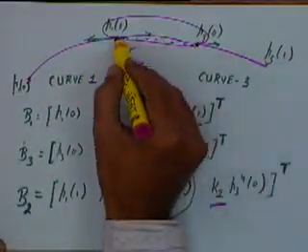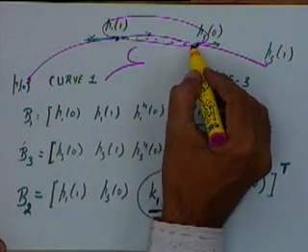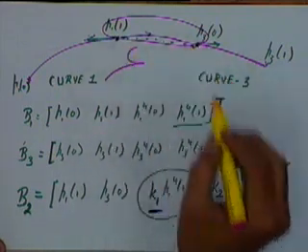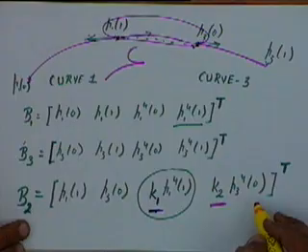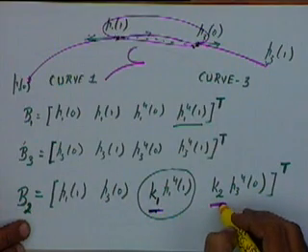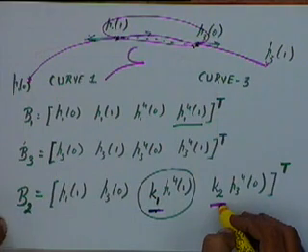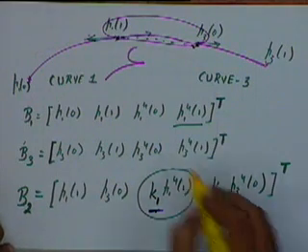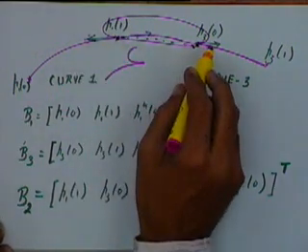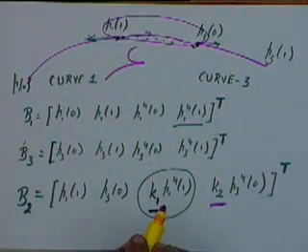Okay. So in this particular case, if you have two curves and you want to get a cubic curve in between, to ensure that continuity, you can use this formulation and get two parameters k1 and k2, by modifying which you can get your C1 continuous PC curve between these two curves. Any questions up to this point?